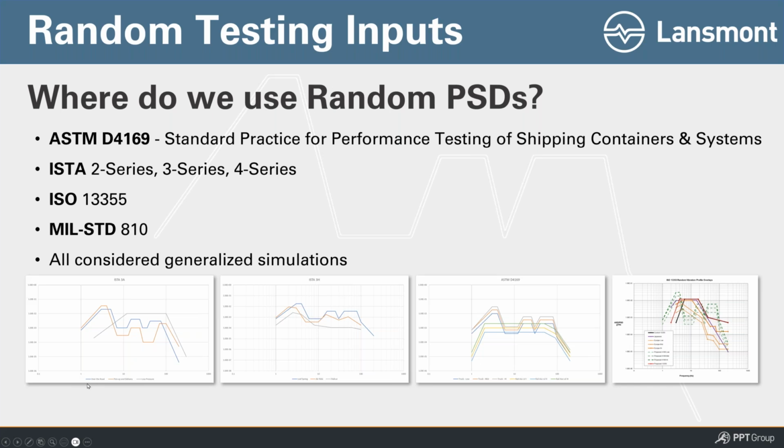Within these, you see there are different traces and shapes: over the road, pickup and delivery, low pressure test, meaning more like an air test, leaf spring profile, air ride profile, rail car profile. So they are these generalized PSD profiles that, once again, simulate the energy content that you could expect to experience if you ship using those different modes of transport. We call those generalized simulations or general simulations.